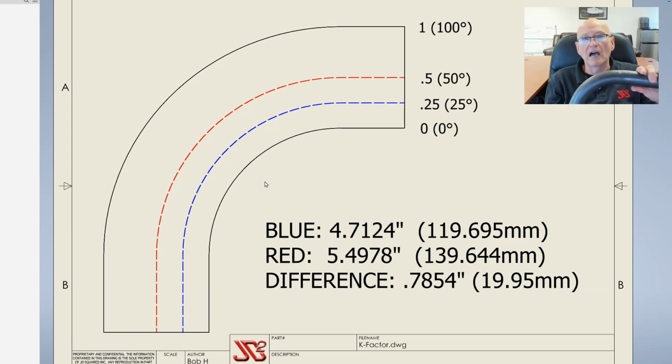The achieved centerline bend is typically larger than the die set that you use to bend it. So say, for instance, we used a 5-inch die to bend this. It looks more like a 4-inch die, but it doesn't matter. Well, if we bent that die, if you've ever bent tubing before or sheet metal, you've seen it spring back. It springs back out a little bit. So typically on tube like this, 1.5 inch tube right here, on that particular radius, we're going to get a spring back of about 1/8 of an inch. So even though we bent it with a forming die that was 4 inches, let's just say 4 inches, the achieved bend, where it actually bent, if we measured it, is 4 1/8.